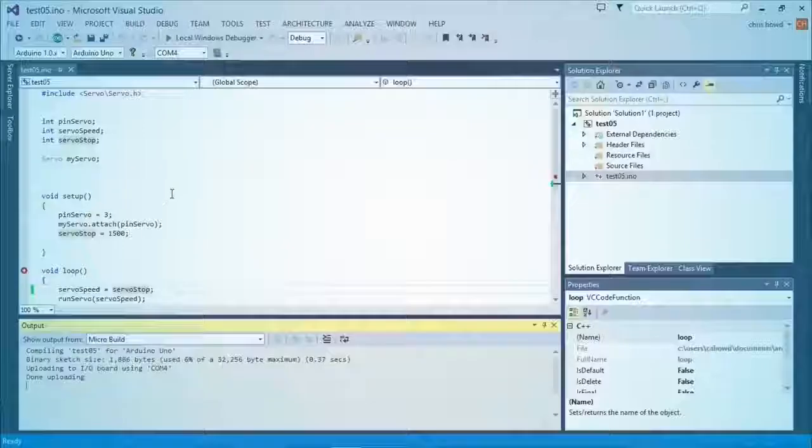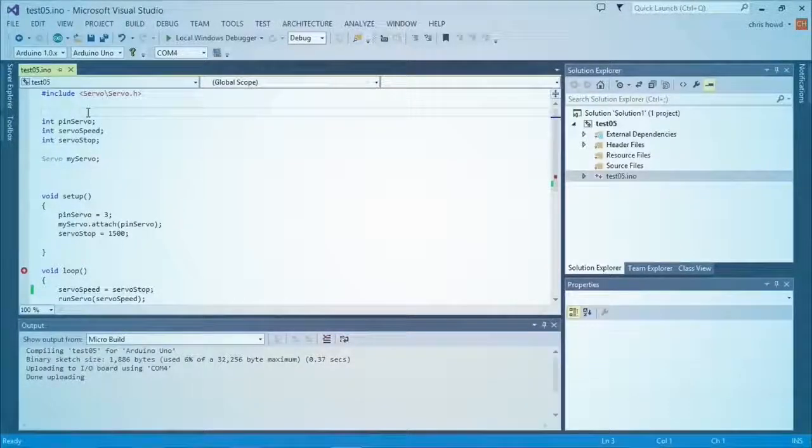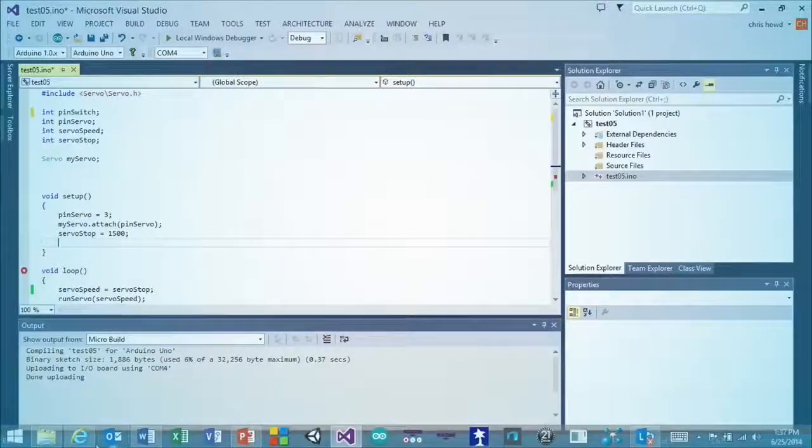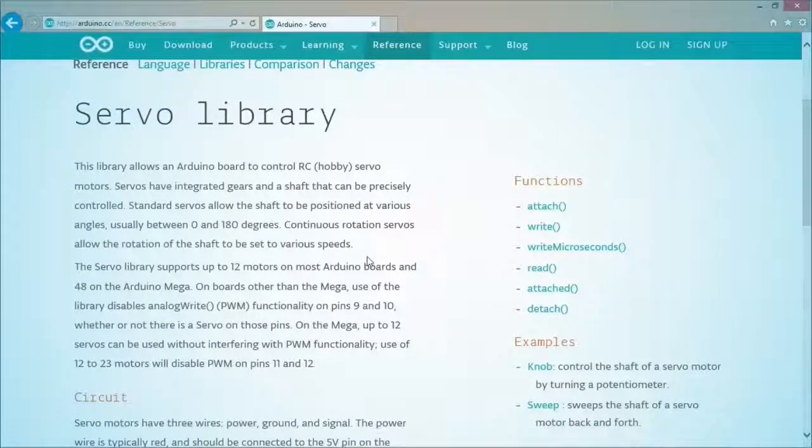So anyway, now our next step. We're most of the way through this demo, but we're going to do a little bit more. We are going to add another digital pin. We're going to read the switch, and it's set up off of pin 10. We are going to say int pin, we'll call it switch. And then down here, Paul, there's another little trick. I am going to switch over here real quick. I am going to go back to language reference.